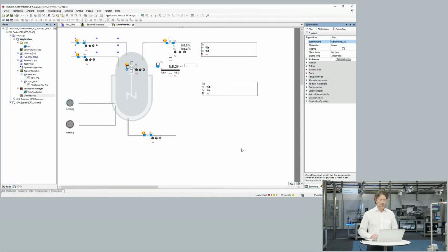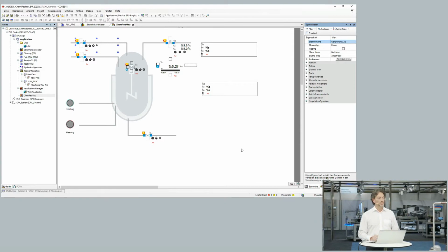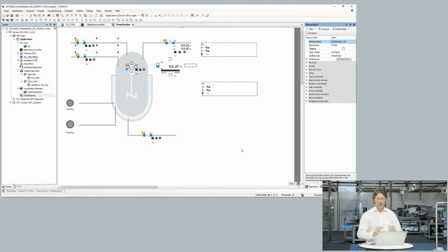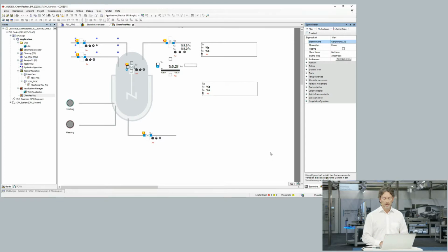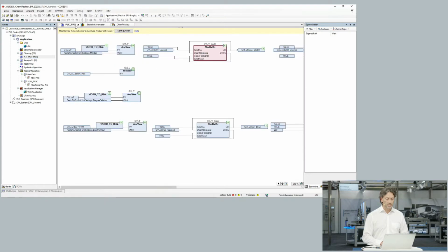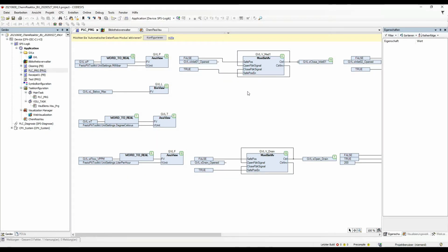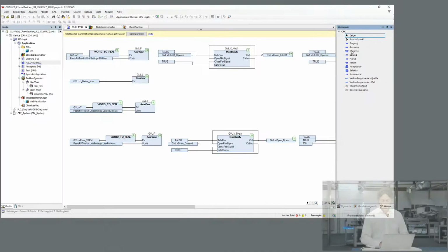And talking about the PA toolkit, I would like to show you now how this is working. So I will go to my environment system. This is our CODESYS environment system, and what you have just seen on the tablet that Alex was using is in fact the visualization that we have here. If you are accustomed to CODESYS, this is nothing new for you, how this is really working. We of course need, at the beginning, a program. This is the logic where everything is being handled in the package unit, and this is something very easy and straightforward to program in CODESYS.